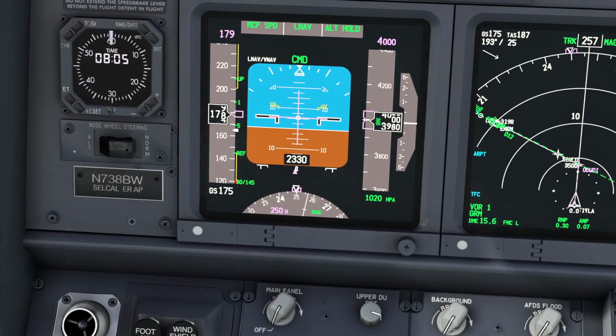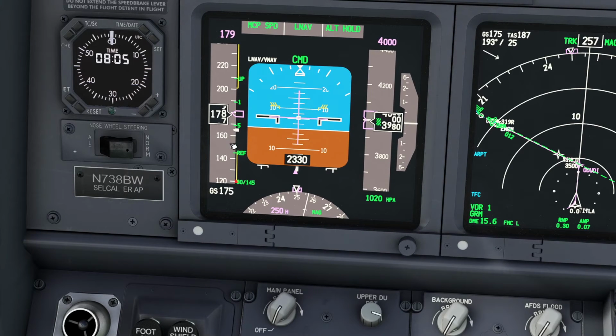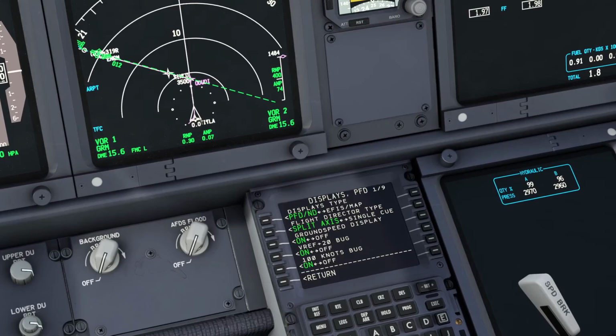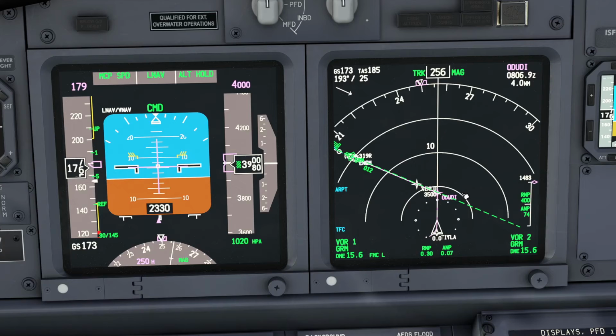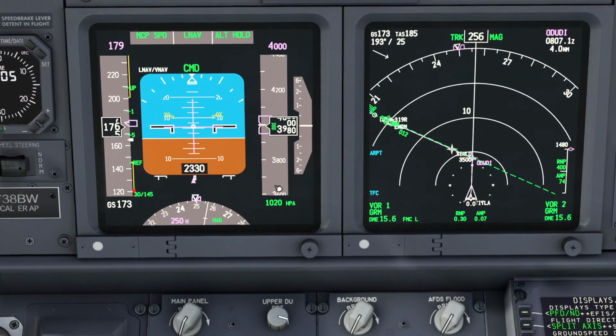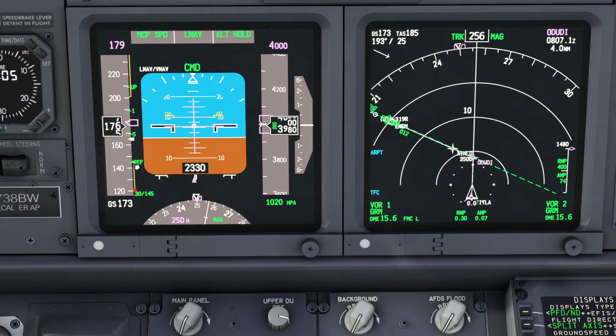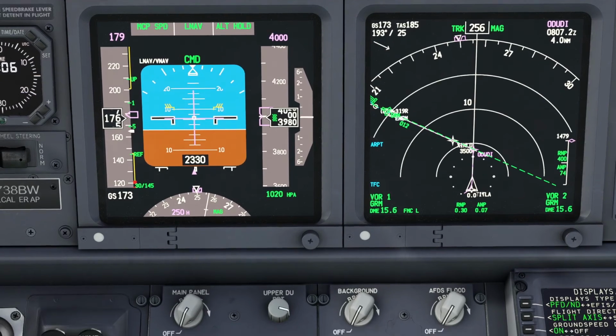This is basically the speed that you are going to fly in case you lost one engine during the approach already with the landing flaps and you choose to land with flaps 15. So you are configured for landing flaps 30 or flaps 40. At this time you lose one engine, you do not have thrust to maintain flaps 30 or 40, so you have to retract your flaps to 15 and still continue your approach, so you don't have to worry about your airspeed or calculating a new VREF speed. Just take your speed to the white bug there and you are going to be fine.